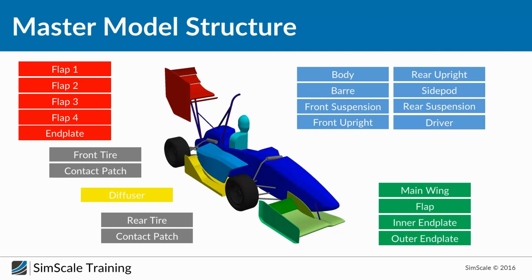What we suggest from experience, especially if you're working with complex geometry that has many components, is that when you convert from the precise surface, no matter what format, like STP or any other format, to the STL format, it's really important to take every single component as a separate solid.